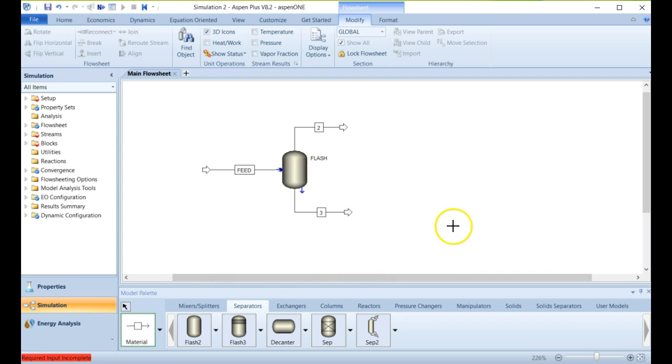So now that we got all of these connected, we know we're happy because the flow sheet right now is blue. It no longer has a little red thingy because all the streams it knows it needs are connected. And if I create a new stream, you'll see the flow sheet becomes red because I've just created a random stream that has an input but no output, so there's nothing connecting it. This is a stream in virtual space that's just going nowhere, and it doesn't like that. So for as long as we have streams doing this, or blocks that aren't connected, this will be red. But once everything is connected, that turns blue and it's happy.